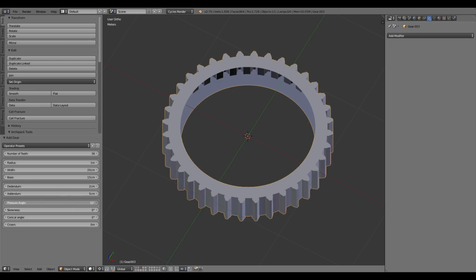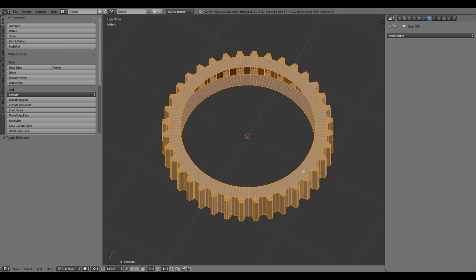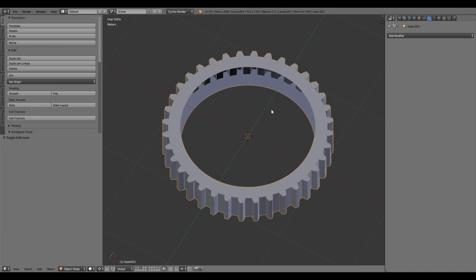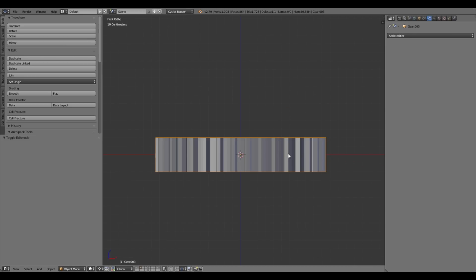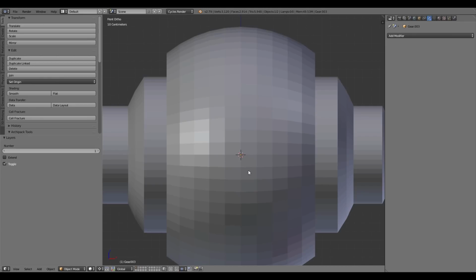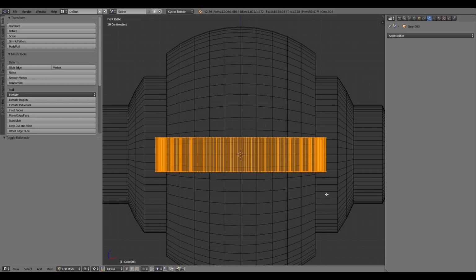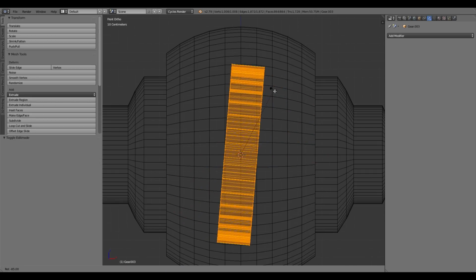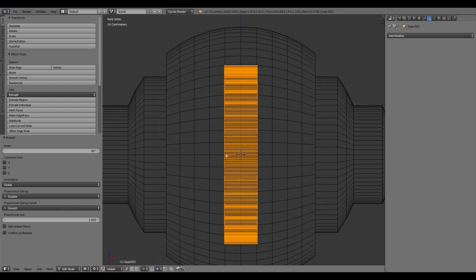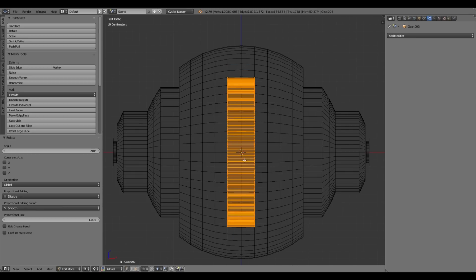And now the pressure angle, right? That's the top part of that gear spoke. And so maybe we can leave it at about 25. Okay, I'm very happy with that particular gear, so I'm going to go into edit mode and out again, and that commits that to the gear. So let's move this M1 back to layer 1, where I'm going to go into edit mode and rotate this around, and leaving that pivot point in the center. You'll see why in a moment.